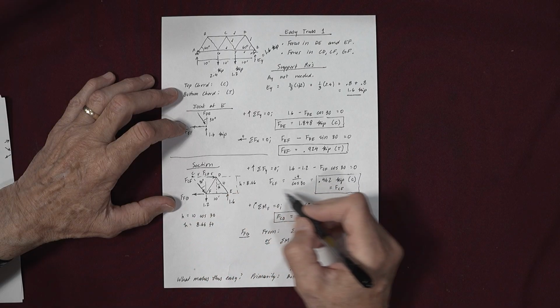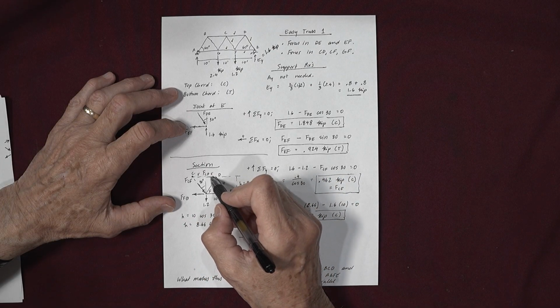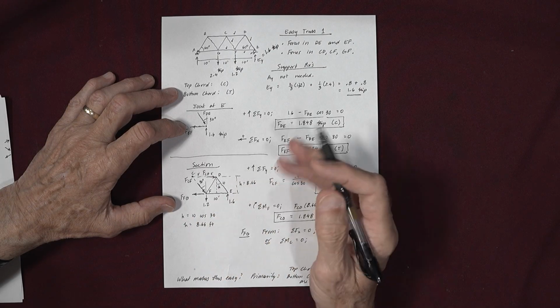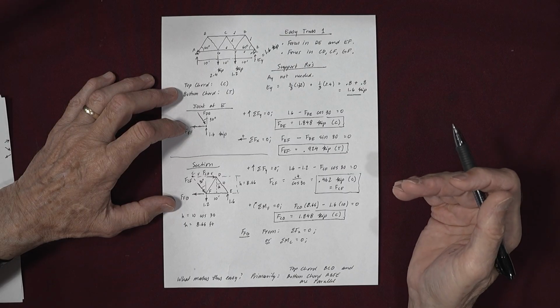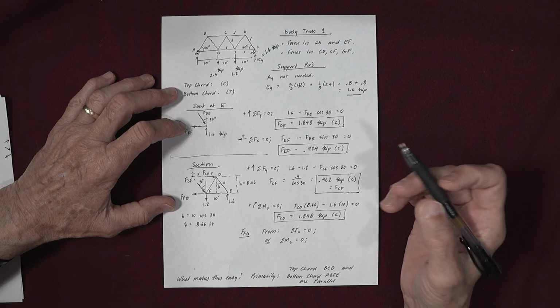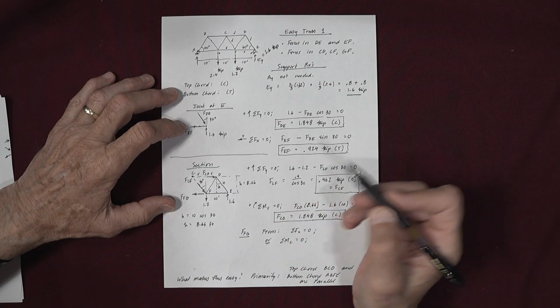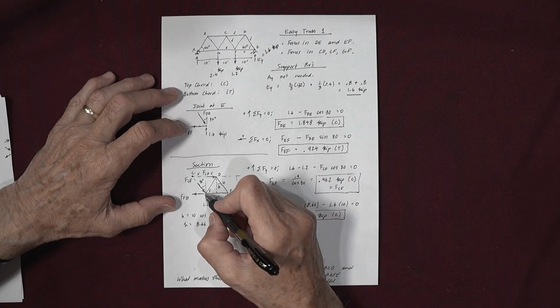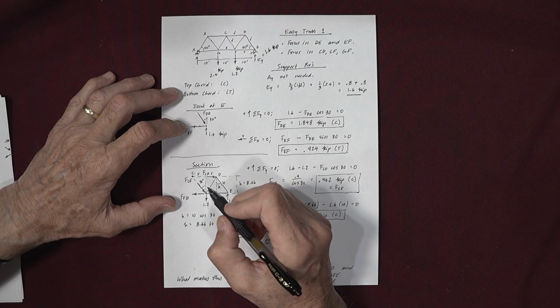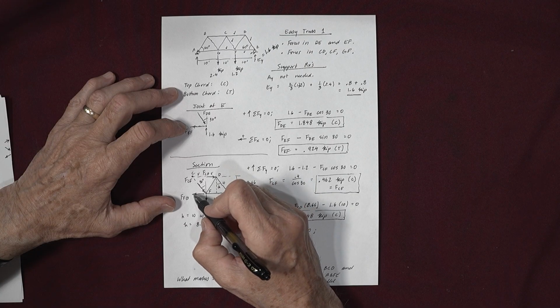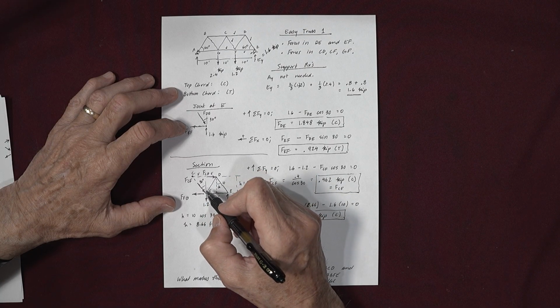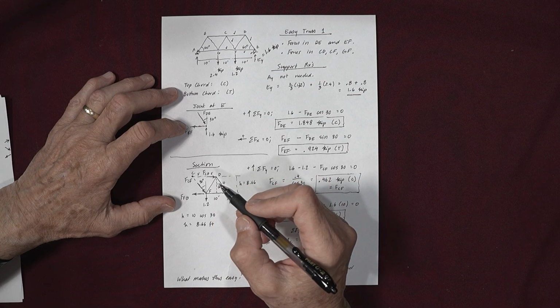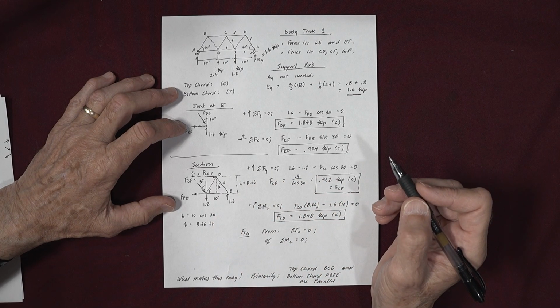If we started with an x equation, then we'd have three unknowns with x components. So start with equations that will get you something. Our next equation will sum moments about F right here. If we sum moments about F, then you basically have two unknowns at F and just this one unknown up here, so we have two terms in that equation.